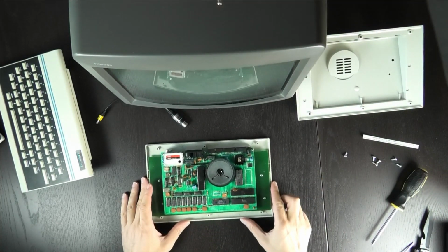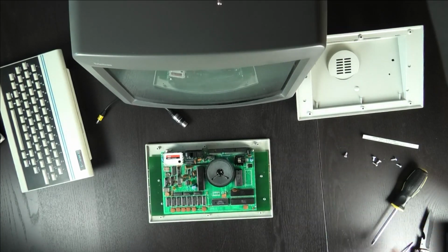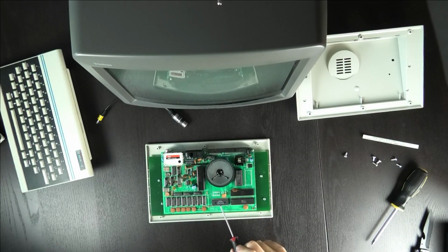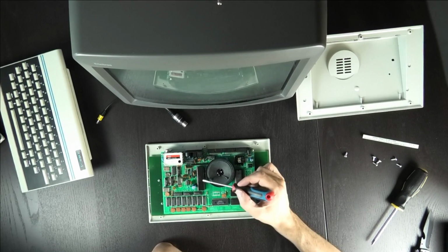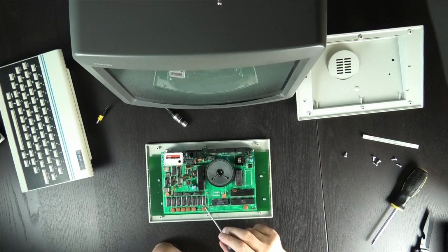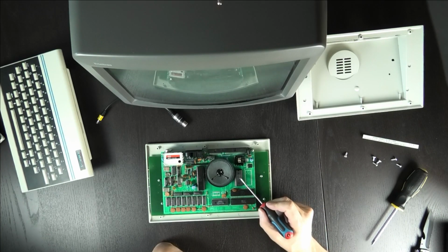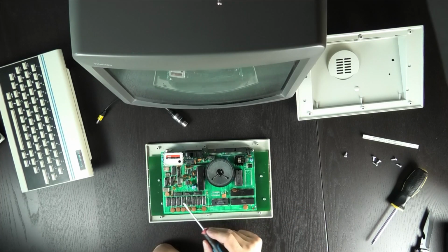So that's your 48K Oric. Here we have the sound chip, the AY-3-8912. We have the CPU, the 6502. Here we have the VIA, SY6522A. Here the graphic processor, the HCS ULA, uncommitted logic array. And here we have Oric Basic version 1.0, and here we have the 64K of RAM.